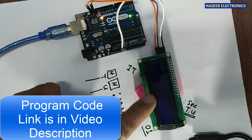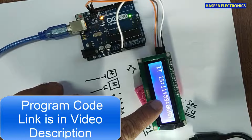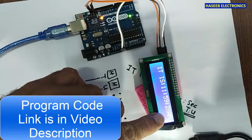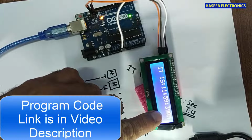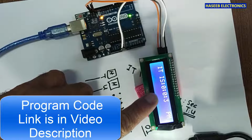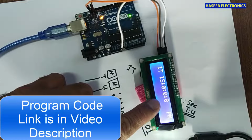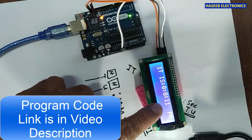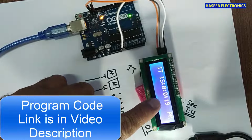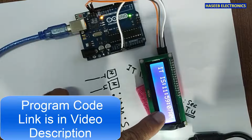If I reset it again, it shows 11:59 because I provided a preset value to this point, so that we can see what the current condition is. And now I will show the previous condition. In video number 707 we wrote this program. It was a simple clock, but the problem was a leading zero problem: when it is 01, 02, it is not counting in the units and tens. At that time it was showing just 1, 2, 3. After modifying the program, now the code is working like this.